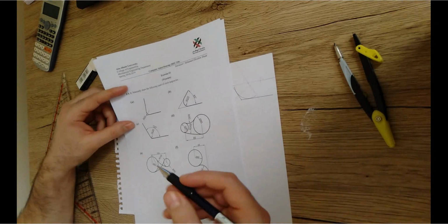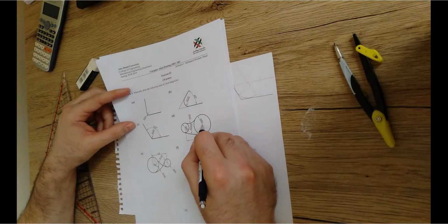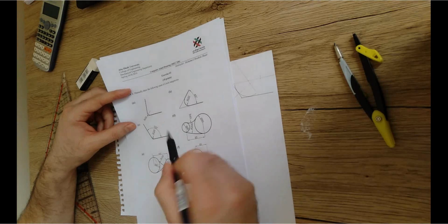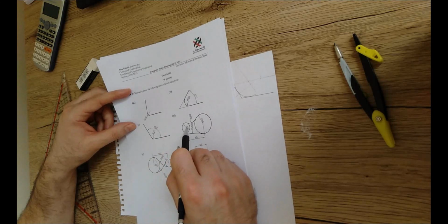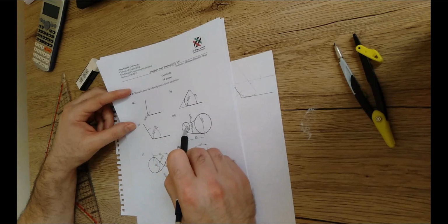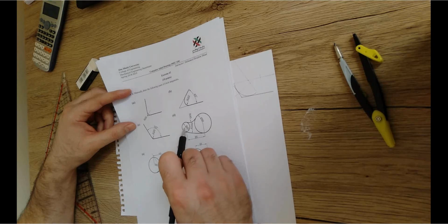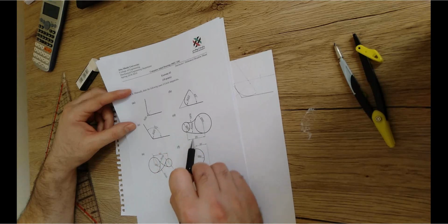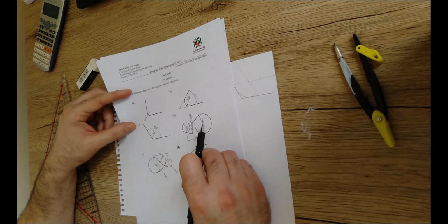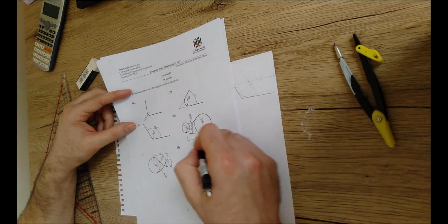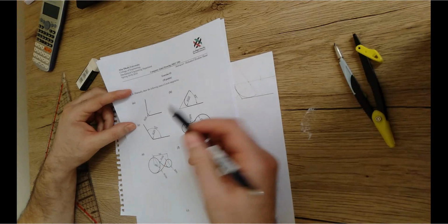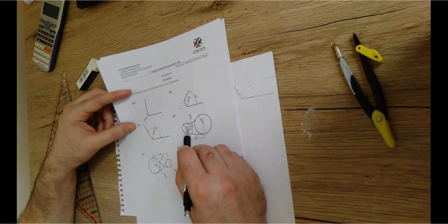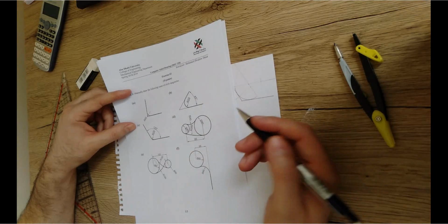And you should keep in mind, to draw the circle, we have to look at the center point of each one. So let us start, if we decided to start by drawing the small circle. So we're gonna pick any point to be the center point of this circle. Then we're gonna draw a horizontal line and measure 85 millimeter to locate the second center point. Then we just definitely gonna draw the two circles. The diameter of the first one is 40, the diameter of the second one is 80.